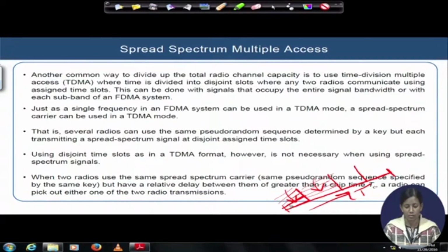Once the data transmission is over, as these pseudo-random sequences are orthogonal to each other, they are disjoint. So, a sequence can be repeated over multiple time slots like this. The number of codes required to operate is really not as high as in CDMA. It is a nice situation, but definitely TDMA involves a high delay and a waiting period to get access to the channel.